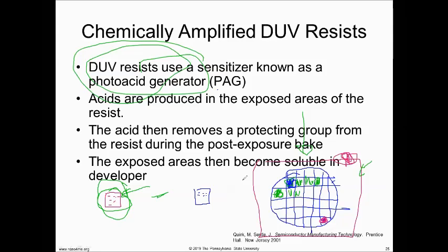Well, I can't do the whole wafer at once because I just can't do that. I still have to stick to the single die at a time. So what I can do is change my resist so I don't do an exposure in 6 seconds. Maybe I can do an exposure in 1/10 of that time.